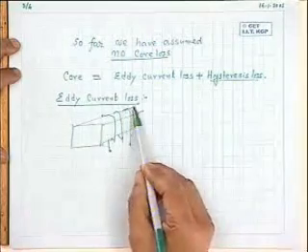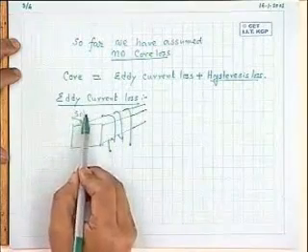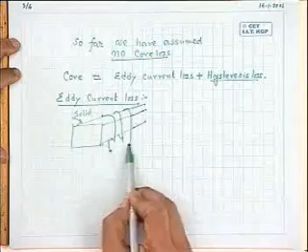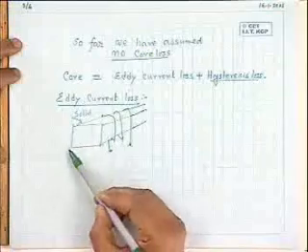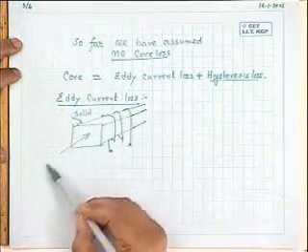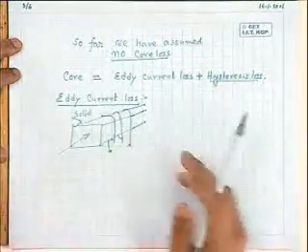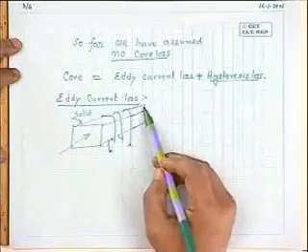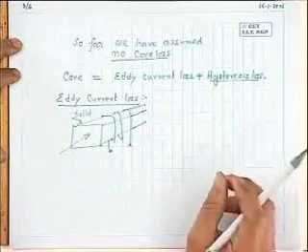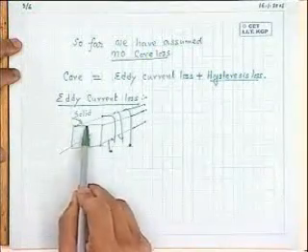It is a solid magnetic material. Now if this coil is energized from a single phase supply, then the flux will be produced along this direction. Of course it will sometimes go from left to right or from right to left, and its value will change with time. And if any other coil is wound on this same magnetic structure, we know there will be induced voltage that can act as your secondary. But let us for the time being forget about other coils.